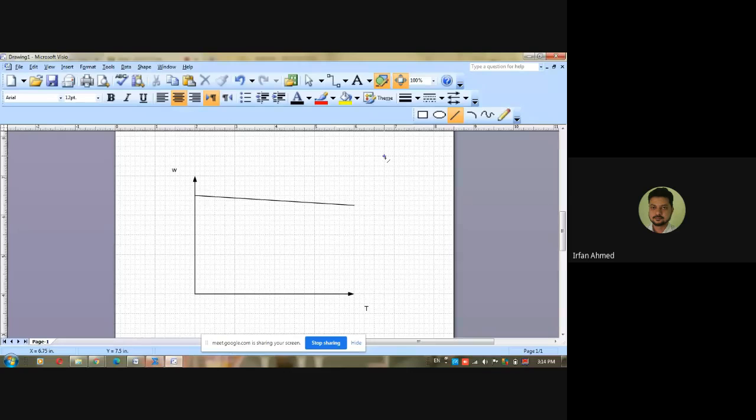Because the torque is proportional to flux and armature current, and your flux is constant here. If you vary the load, your armature current will change. Okay, anyone else? Sir, we will decrease the load and take the reading, increase the load and take the reading. So we will take 2 points and connect the line. Yes, that is the answer that I am looking for. You have learned in school that to draw any straight line, all that you need is 2 points. So why continuously change the load when all that you need is 2 points?